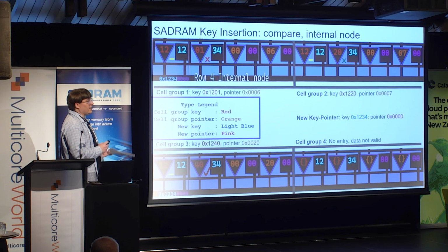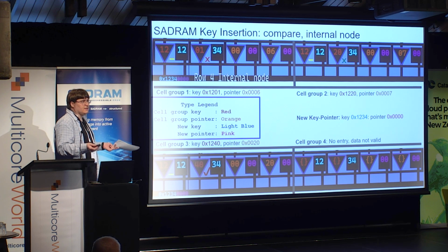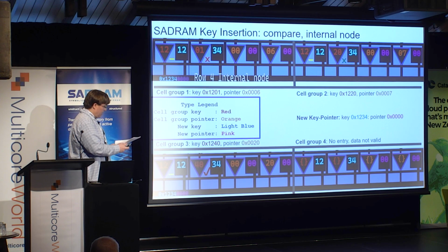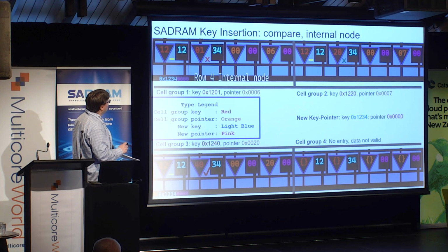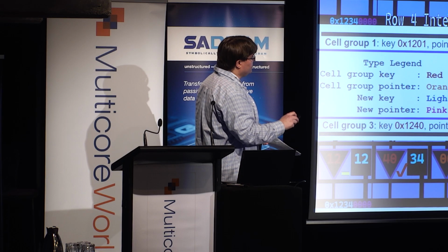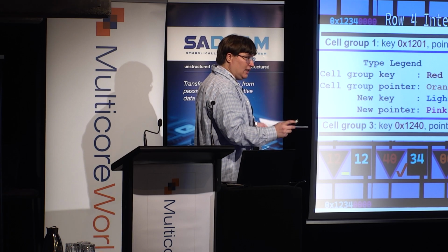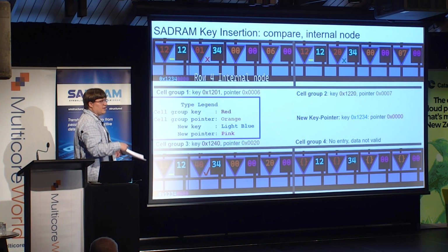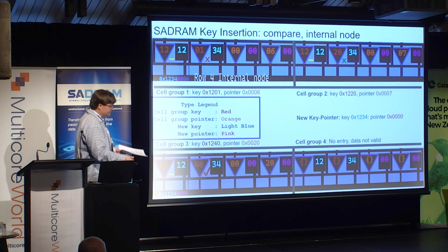These are pictured as being able to store 8 bits. Obviously, that's not true because they're 1T, 1C cells. In actuality, these are 1-bit cells. They're pictured here as 8 so that we can track numbers as I walk you through the example. The other thing to note is we're broken into 2 groups. The row buffer exists on 1 line, so this is 2 chunks of 1 line, and there are going to be 128 or 64 of these cell groups on the row buffer.